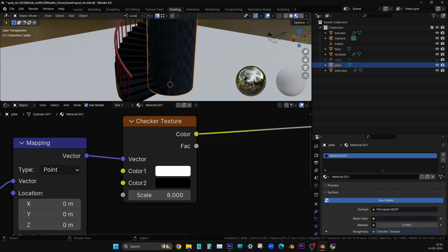Always in Blender, this light we have to increase so much. Generally the watts will be very low, 10 watts, 20 watts like that, but it is not at all enough. So what you have to type is some thousand or something. Now press Z. It is in rendered mode.